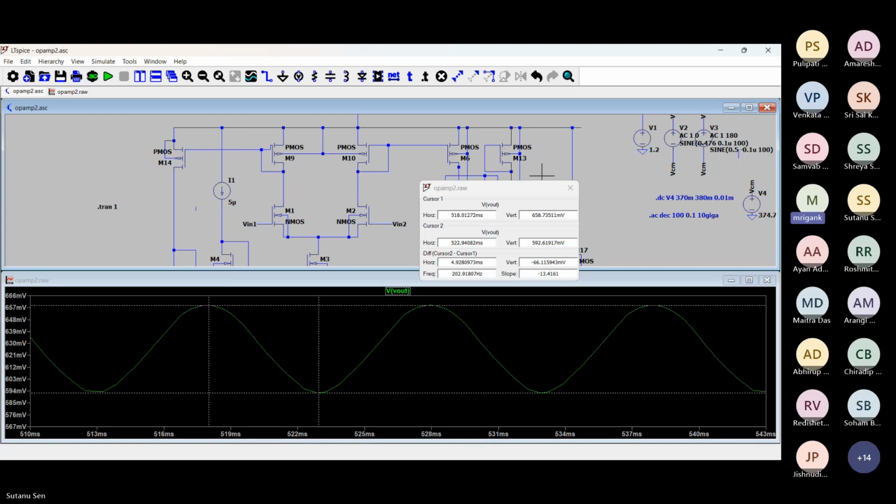Here, in the two parts, there is a good amount of asymmetry, but still the gain, and the other thing is the gain of the first stage is also limited. Because of that limited gain, it's possible that the two paths are having asymmetry, and even the gain of the second stage on the left hand side is also less. Most of the gain is coming from the output stage. Yes, so because most of the gain is coming from the output stage, a difference in the input of the first stage, the DC level input difference, is not translating so much to a difference in small signal currents.